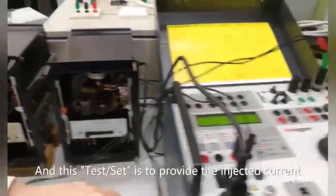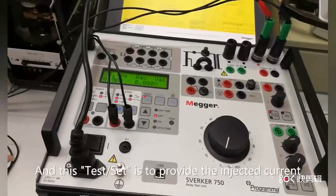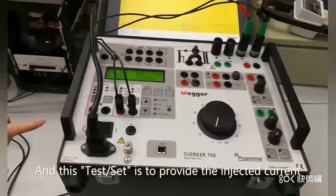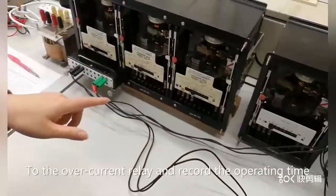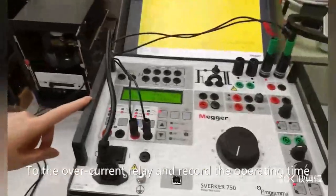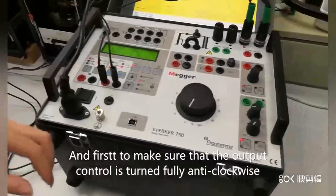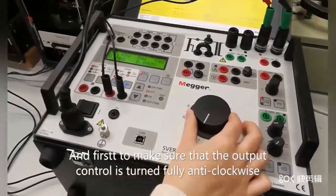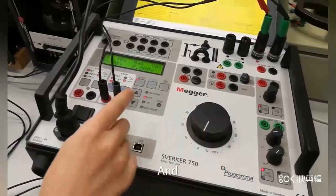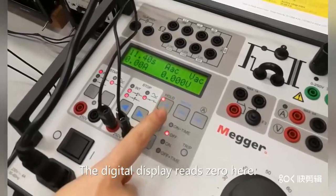And this test set is to provide the injected current to the overcurrent relay and record the operating time. And first, make sure the output control is fully anti-clockwise, and the display reads 0.